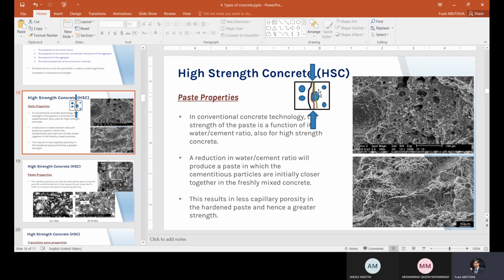If you see that the aggregate particles are not broken, and the failure went around the particles and reached the other parts, it means that the weak point in this mix was the transition zone between the aggregate and the paste itself.